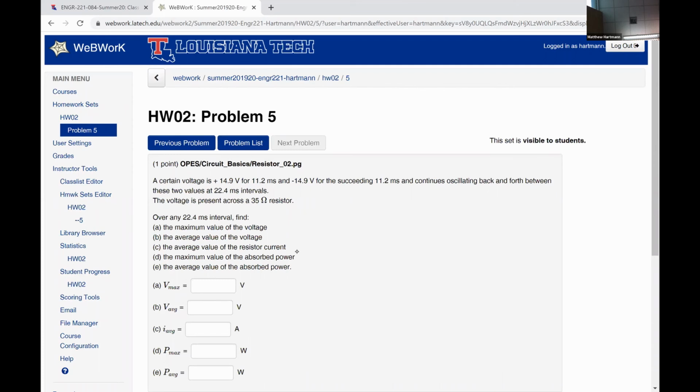6.343 watts of power. So even though the average value for the voltage and the average value for the current are 0, the average power will be V squared over R. And it's because when you take the power that way, it doesn't matter whether or not your voltage is positive or negative, the numerator is always going to be positive.